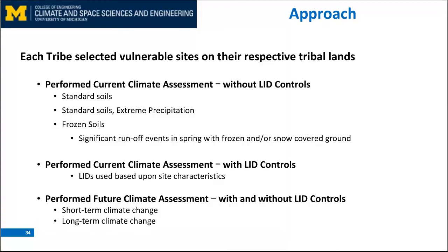And then in the northern Great Lakes region in general, but particularly as you go farther north, throughout part of the year, the soils are often frozen or they're often snow-covered. And so one of the things that's really nice about the Stormwater Calculator is the ability to change the values of infiltration for a particular site that you're doing. And so that is one of the things we did, and I'll show that briefly.